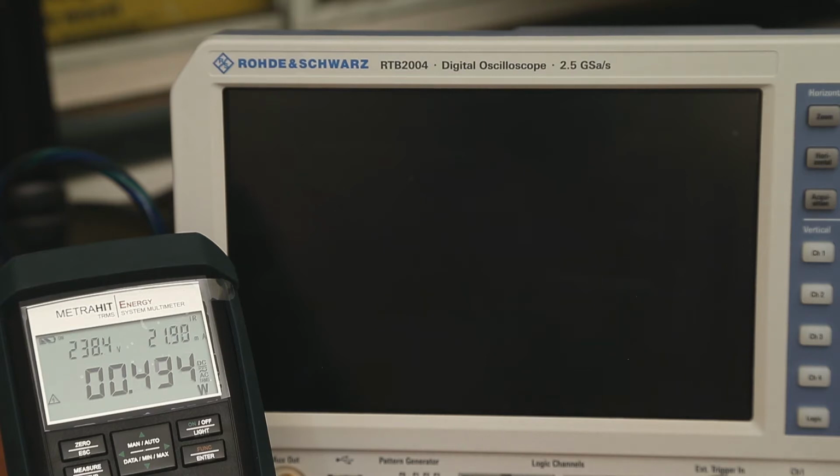Even when it's in my lab and I switch it off, I've got a master switch that switches my power feed off to various items like a function generator and the scopes, etc. So I don't tend to leave them powered on all the time anyway. I just don't see the need to. If I want to preheat them, I'll put them on and leave them on for half an hour before I start measuring anything, and then when I finish for the day I switch them off.